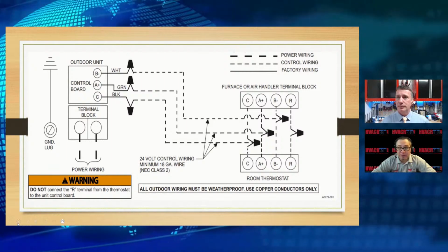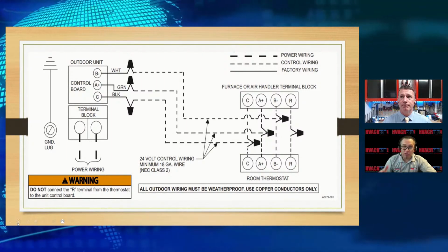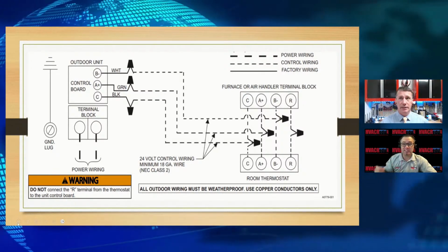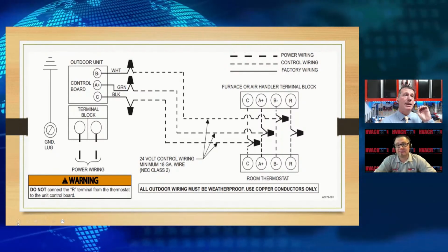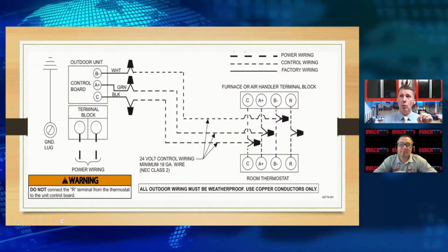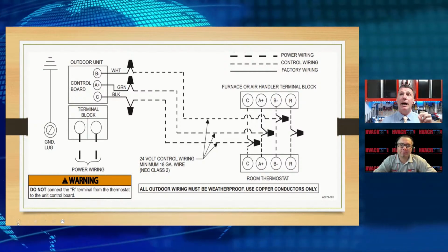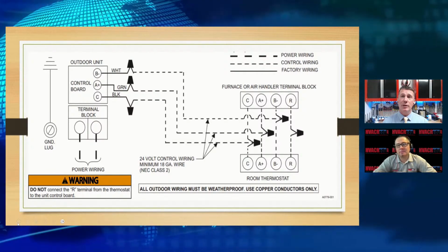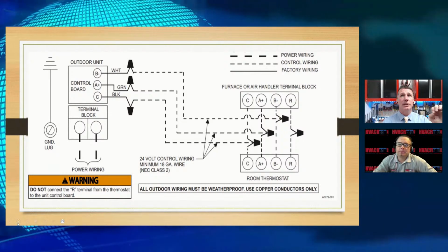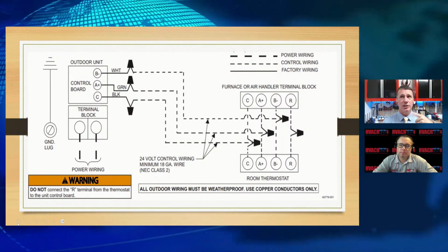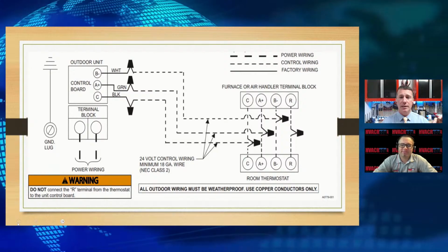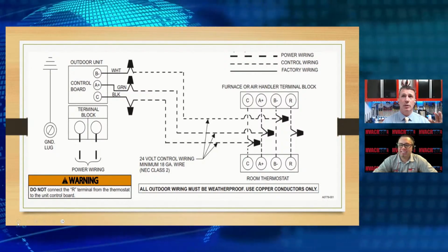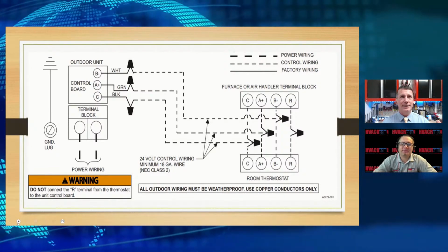It's being delivered to one controller or the unitary devices in the same way, just a different language. Now, I will say that I cannot speak for the bias voltage between 1 and 2 for the rest of the manufacturers. I know the Climate Talk pretty well, and there's a lot of training material for that. So if there's anyone out there that has tested the bias voltages and knows more about the bias voltages between different manufacturers, I'd love for you to hop on, because that's a piece that not every manufacturer likes you to disclose. I'm curious myself, but I've got my own ideas.